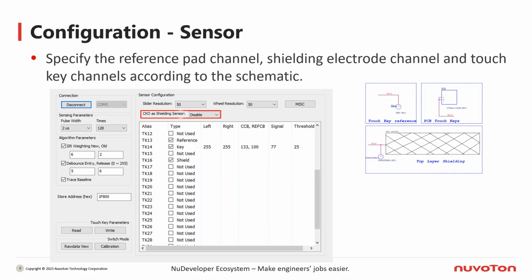In addition, you can also select the TK_SE pin as a shield. The third and fourth columns are to set the shielding compensation of the pin. These 2 columns are not mandatory options. If the signal strength is not enough, you can set the left and right of the key as shielding for compensation. The left and right here are not necessarily the left and right in the actual position. It is just to select 2 compensation channels for it. The number N filled in represents the pin TKN. The 4th, 5th, and 6th columns are the parameters obtained after channel calibration.